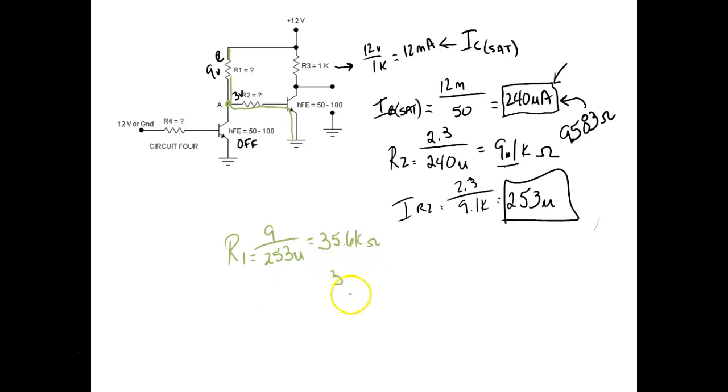Okay, 33 kilo ohms. So what we're going to do is increase our base current, which doesn't hurt. So the actual base current, this guy here is going to drop a little more voltage, and this guy here is going to drop a little less, but still the calculations are going to work out for these sizes. So we're going to use a 3.3?